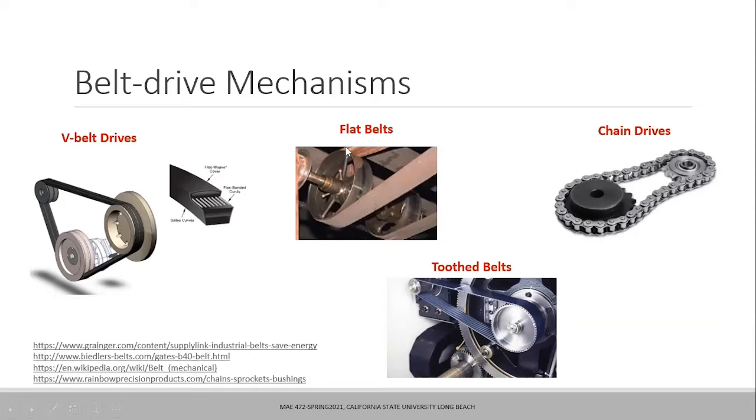And because of the friction contact, you have no control that if there is an overload, if the torque is exceeded, then you may have slippage, and there you don't have any control. But in case of chain drives and tooth belts, you do have control because there is a serration and the teeth are in engaged position. So there is no possibility of slipping of this chain. So there will not be slippage.